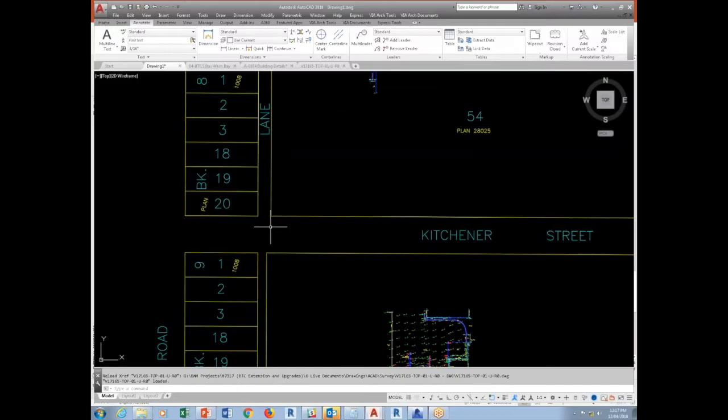The reason why you do not want to have it far, far away is that once AutoCAD reaches certain millions of decimal places, your drawing starts to break down. So when you draw lines or do offsets and certain things, it just will not do it because that number is too huge. So if you set it to 0, 0 and make it closer, it makes it a little bit easier for you. Okay, so your hatches, everything is going to work properly.